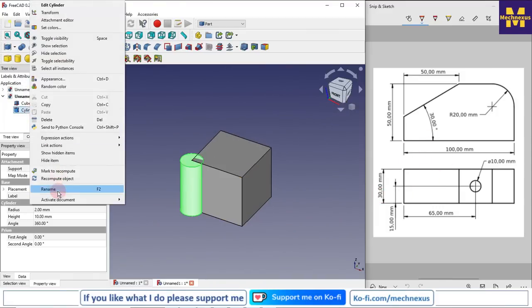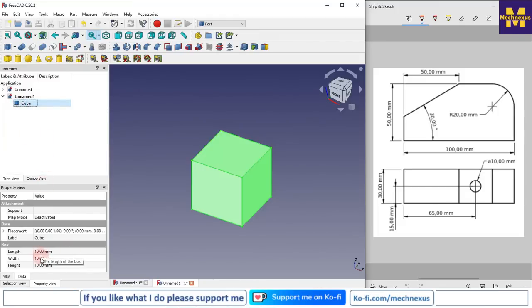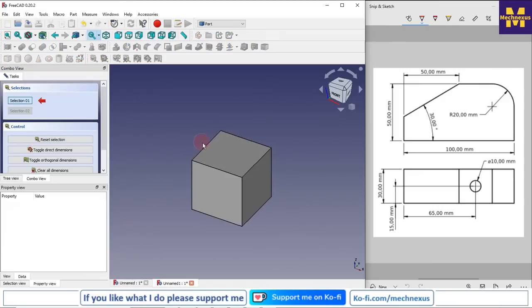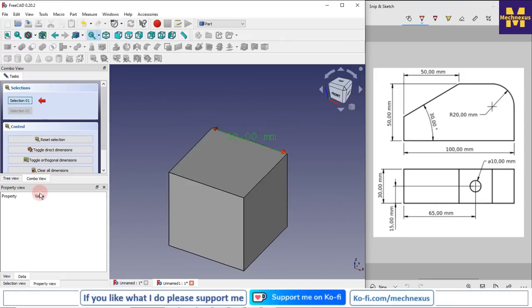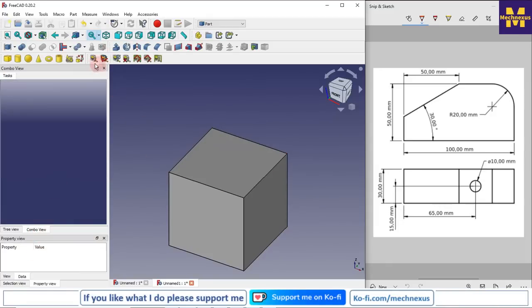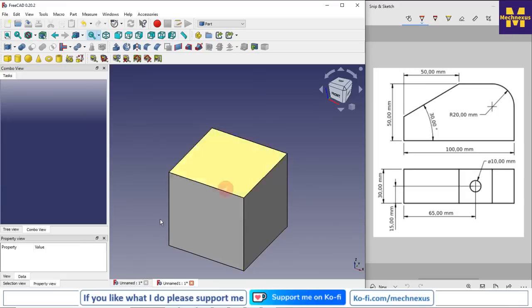Now we will quickly look at the measuring tool in FreeCAD. If I click on my cube, I get my dimension. It is 10 in length, width and height, but I can also check it from here with the dimension measuring tool. I will select this one, so I get the dimension 10. If I want to measure this edge and this edge, yes, you can get the dimension with the help of the dimension measuring tool. So these are the basic tools which we will use while making this part.